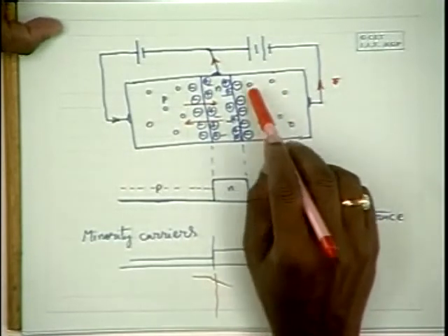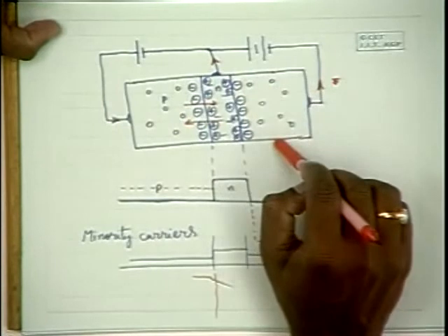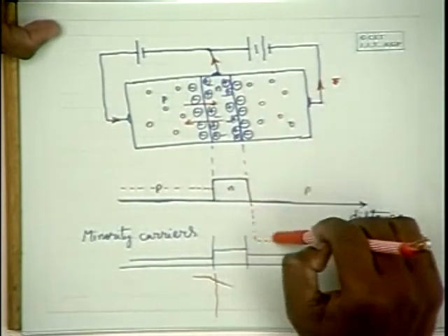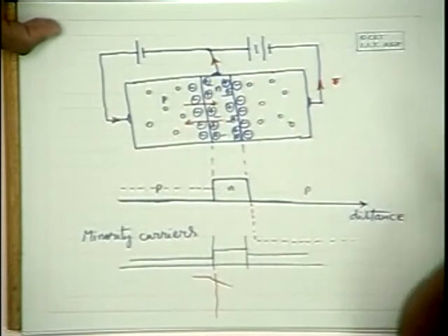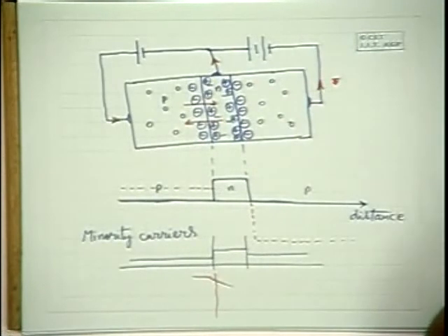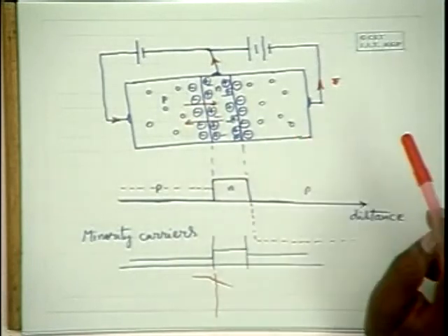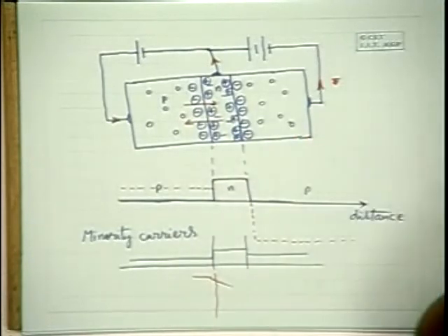So when the doping concentration is low, the depletion region would be large and the potential difference would be large, and the transportation of the injected charge carriers into the collector would be better, because that is desirable for operating this device as an amplifier. We shall discuss it subsequently. Is it clear? Any other question?